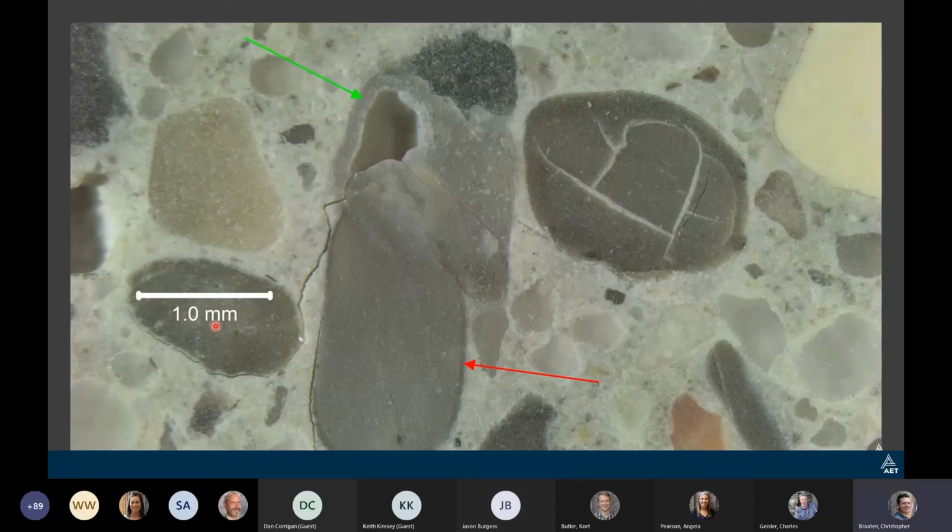But it's pretty cool that, I mean, it's not cool for a ready mix producer. Don't get me wrong. I don't want this to happen to our concrete and have people have to tear it out and start over again. But just being able to see this stuff, it is pretty cool to know what kind of action this can actually have, like the combination of alkalis in the concrete, silica in the shale, creating this gel. And I'm going to get into alkali silica reactivity again in a little bit here and get more in depth in case you don't know what that is yet.